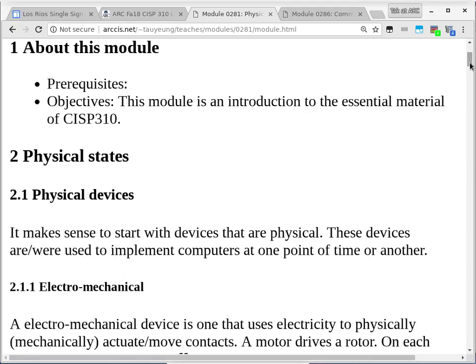And then you look down one level, you see the ALU, and you can see inside the ALU, oh, this is the adder, this is the subtractor, and so on and so forth. You look into the adder, you see gates, you see AND gates, OR gates, NOT gates, and so on. You look into an AND gate, then you go, how do I implement an AND gate? We can use transistors to implement an AND gate, so you start to see the transistors. And we stop there. We don't talk about device physics in this class, but we do get all the way down to transistors.